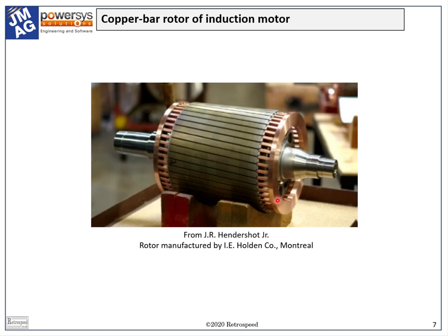The thing to note about this rotor is that there are no connections. It's very rugged, and capable of much higher speeds than a commutator motor armature. Most induction motors of this type use cast aluminium for the cage winding, but for highest performance, especially efficiency, copper is preferred.